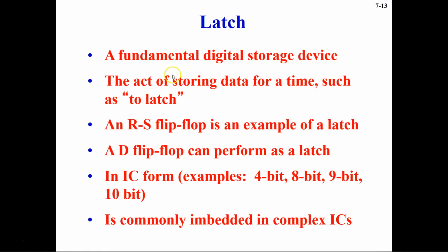So this is latches, and there are a couple of points mentioned here, so I'm going to quickly read them. A fundamental digital storage device is called a latch, and the act of storing data for a time is to latch. All the flip-flops which we saw previously are also called latches. The RS flip-flop is an example of a latch, the D flip-flop is an example of a latch, and the JK flip-flop is also an example of a latch. They are available in different IC forms in 4-bit, 8-bit, 9-bit, 10-bit, etc., and they are commonly embedded in complex ICs. So these are some quick points to remember about latches.